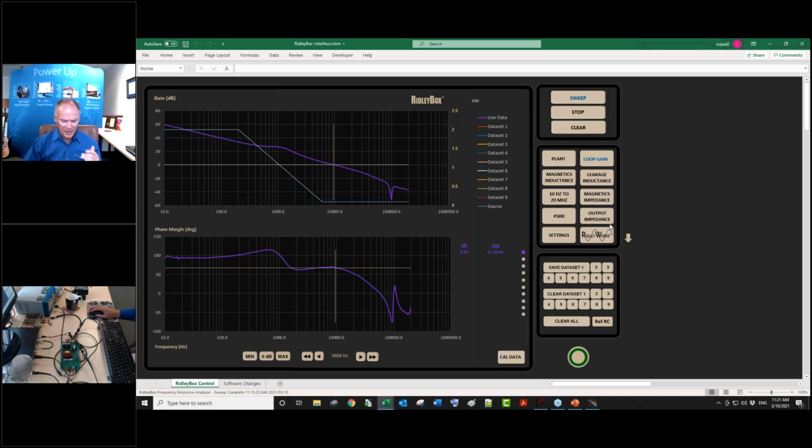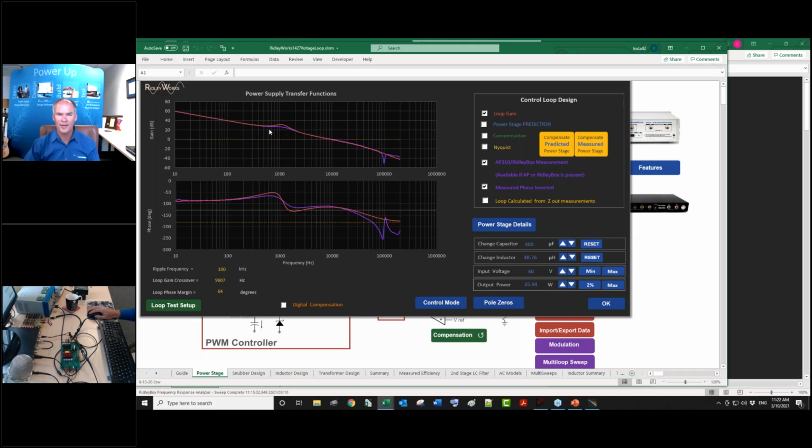In fact, if you go back to the basic model that Middlebrook did and Vorperian did, everybody did, there's all kinds of switch models, there's state space averaging. Every single one of them is fundamentally flawed and wrong. And it misses on this critical part of the Q. This is kind of a big miss. You'd think people would have nailed this by now. How can we be 40 years on from state space averaging, 35 years on from the PWM switch model, and we can't hit the Q?